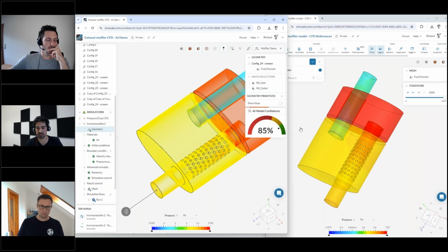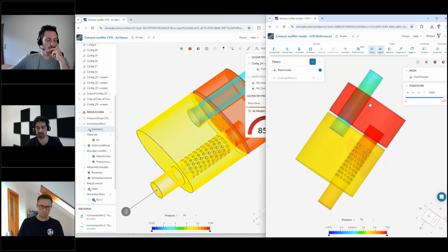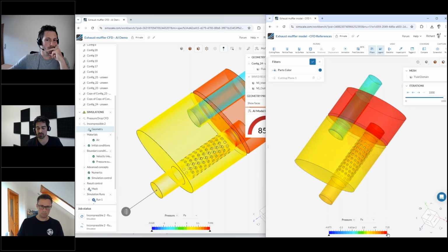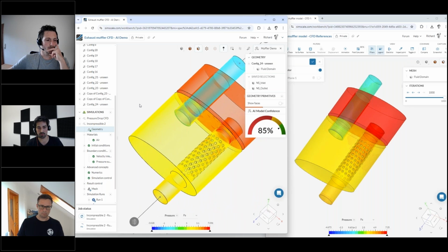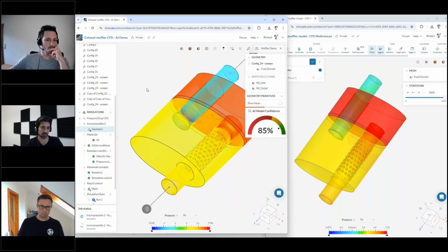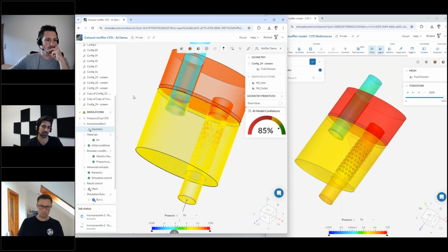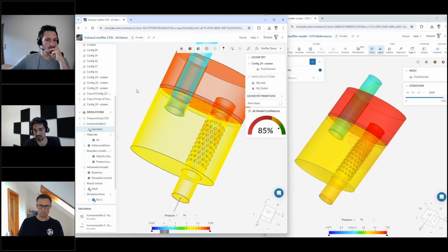And I hope you can see it here side by side, right? So on the right side, that's the traditional CFD solution where we would get 7.25 Pascal. And on our example here, we get 7.1, right? So I think that's an acceptable deviation given that we only waited a couple of seconds for the results for unseen data compared to about 20 minutes for the full CFD.